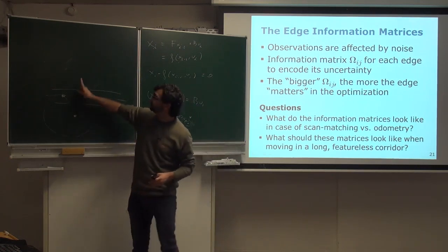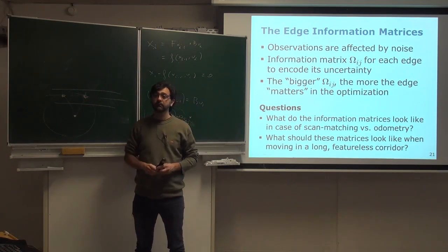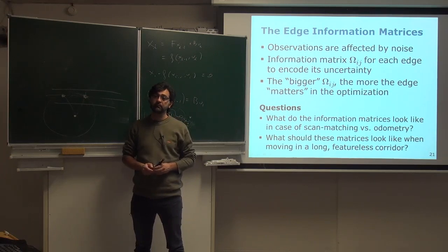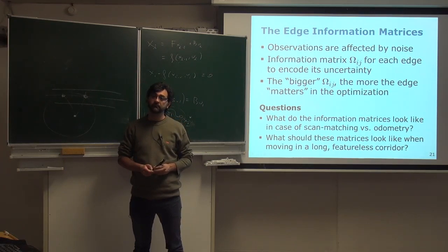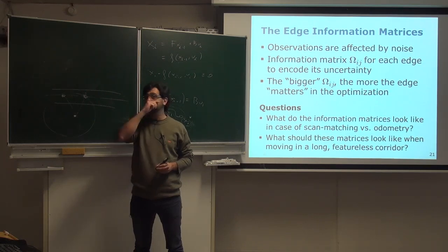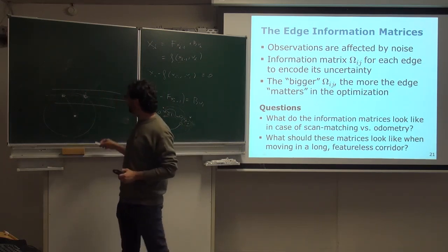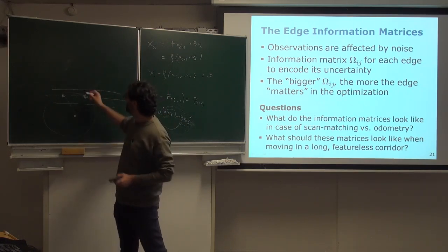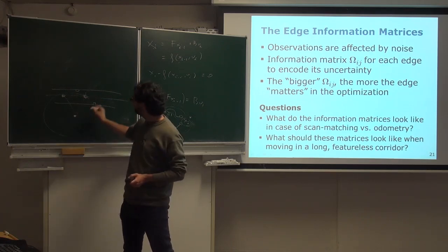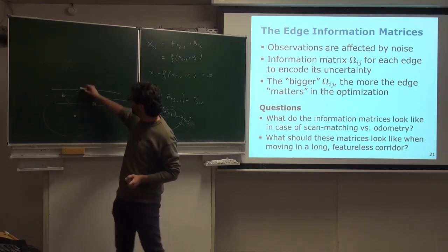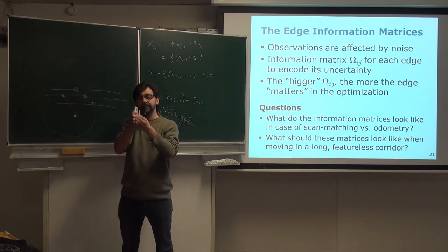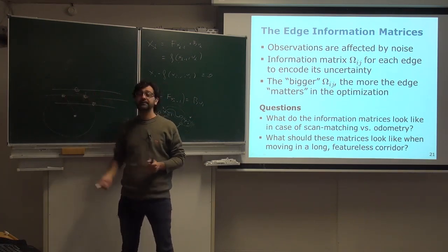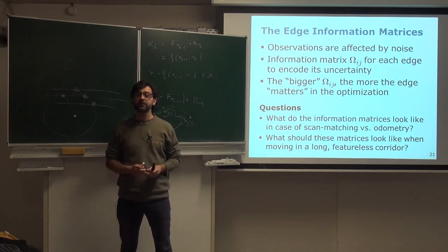But only in this direction. Yes, but in this direction, the pulses get scattered. But in your odometry model, it's maybe a banana-shaped, small scatter, and scan matching, right? Not really. So what might happen is that if you have few features, imagine you see some dents, then this part of the wall and this part of the wall might help you in aligning in this direction. But otherwise, you have no idea where you can be in this direction.